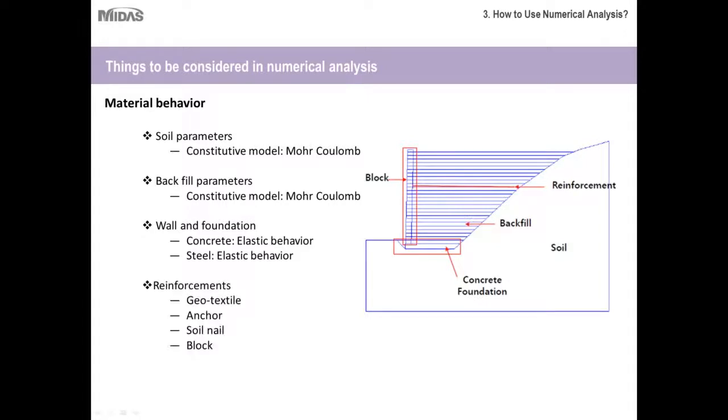And then you can use different types of reinforcement depending upon what type of model you are working on. Is it a 2D analysis or 3D analysis? And you can pick from different types of reinforcement options available, like geotextile, anchor, soil nails, and blocks.